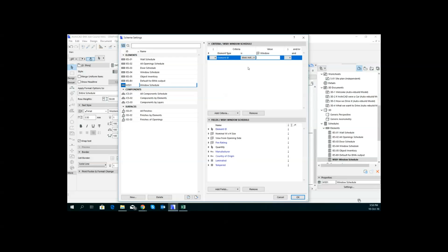And then when I went back into ArchiCAD, that schedule can be added to any element, not just doors or windows. Anything that can have those properties and manipulate data. So it's really handy for that sort of stuff.